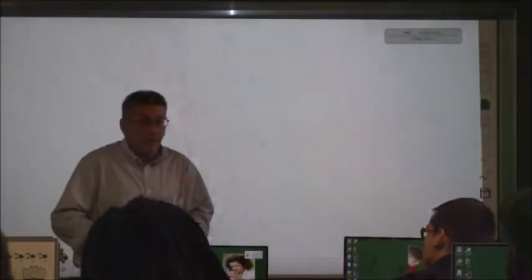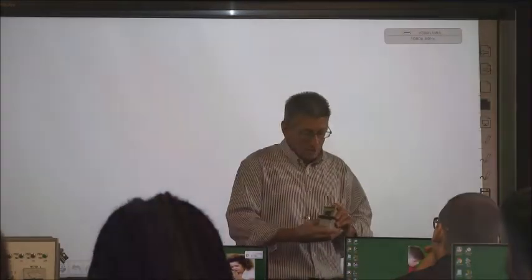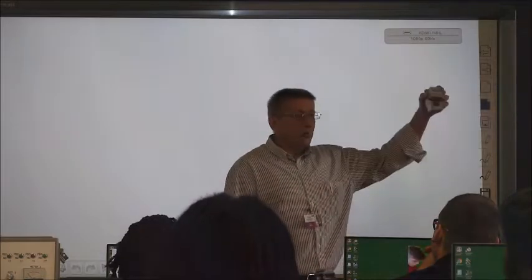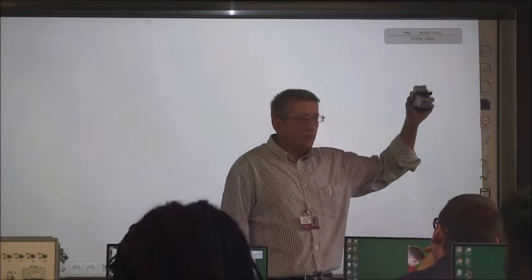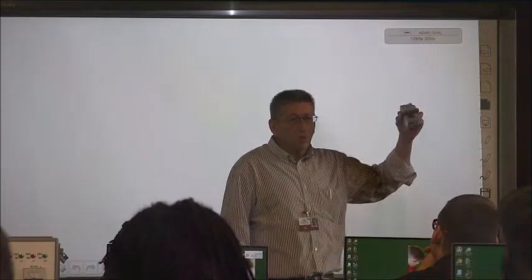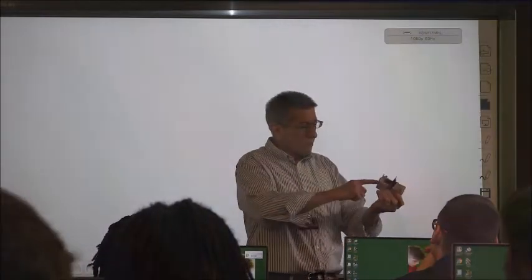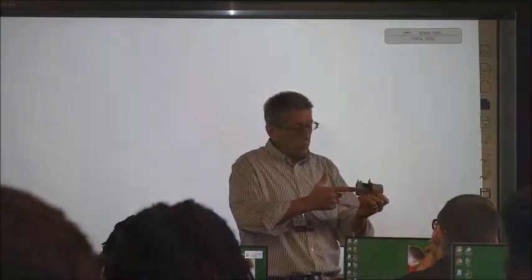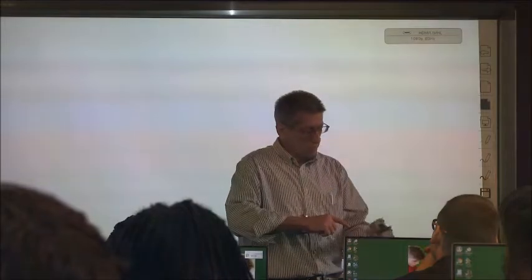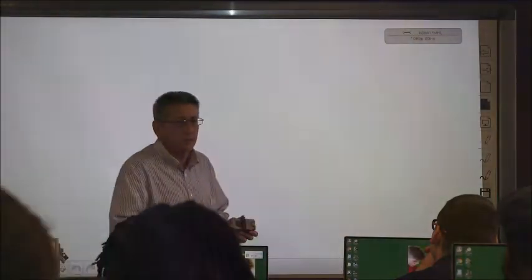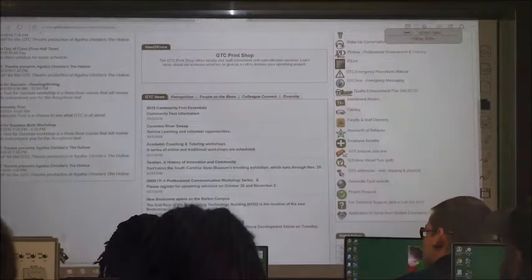There you go. And when I taught motor controls, I taught that too, to the classes here. The new style, as everybody has seen, is the overload relay, and it's adjustable. This particular one is 1 amp to 5 amps. I can't see it, but I think that's what it is. Something a little bit better. So, contact with the motor starter.